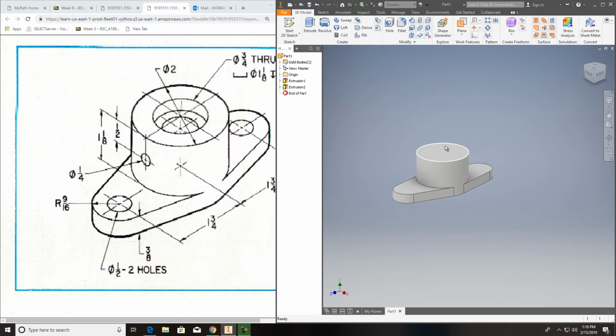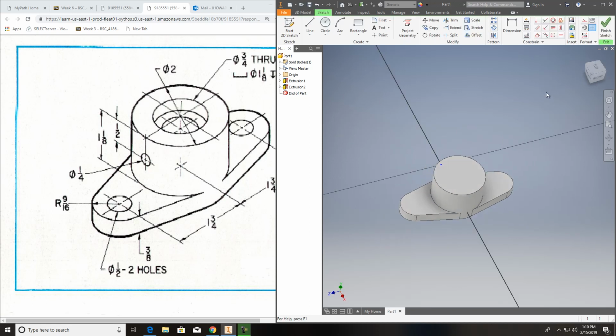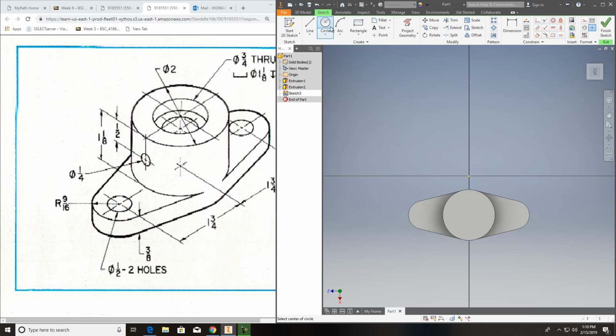Now just put your counter bore up here at the top. You got holes in it. I'll go ahead and get these holes put in real quick. It wouldn't take just a second. And line those up. And I'm just going to roughly, there you go, and kind of hang around here till I get that center point. And those are 9/16, and that is on the radius. So let's make sure I click on that dimension.